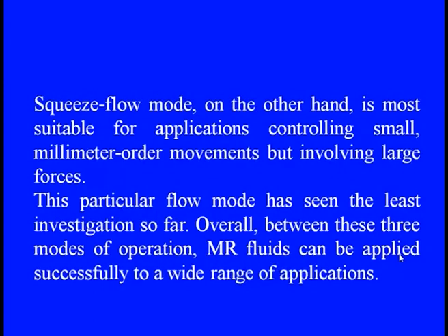And the squeeze flow mode is most suitable for controlling small, millimeter-order movement, but involving a huge amount of excitation forces. So this flow mode has seen the least investigation, yet we can directly control high excitation forces with low amplitude.